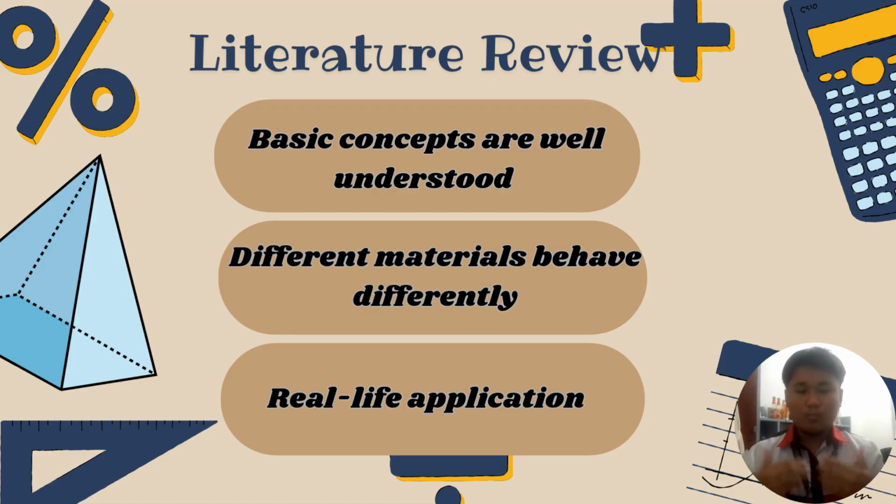In the engineering world, we are always talking about safety. To keep our design safe, we apply a safety factor, which is the yield strength divided by the working stress. This safety factor ensures that we never reach the point where the material is permanently deformed.